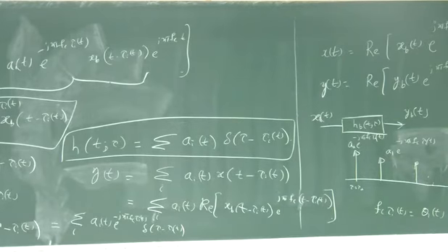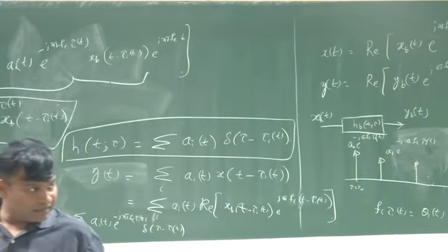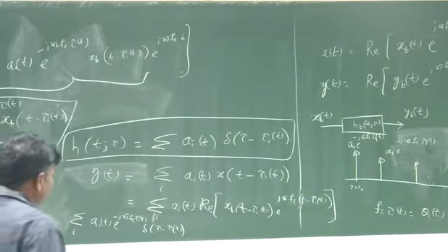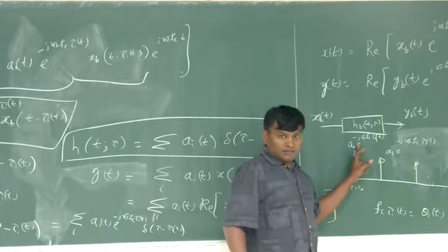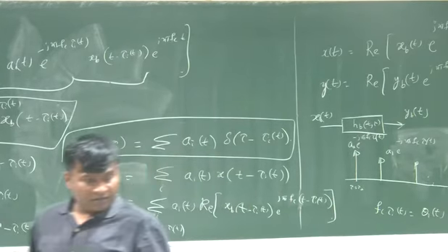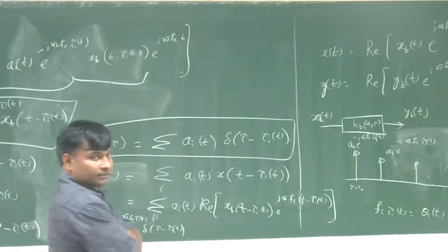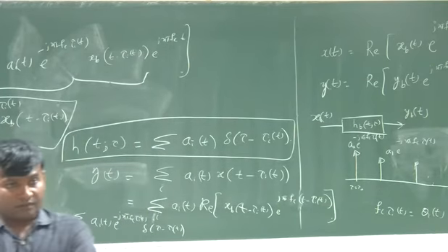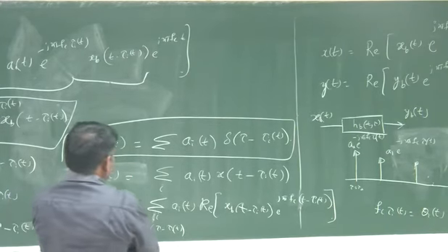So we started with the passband model for a wireless channel, modeled as a bunch of taps with various delays, a real valued channel. And its baseband form is pretty much the same channel except that the phase component comes into the picture. Baseband it generally takes complex values.